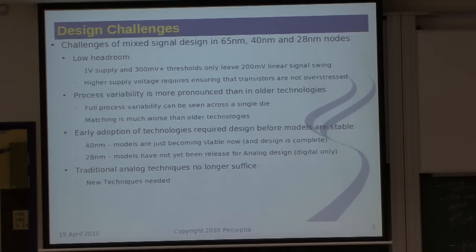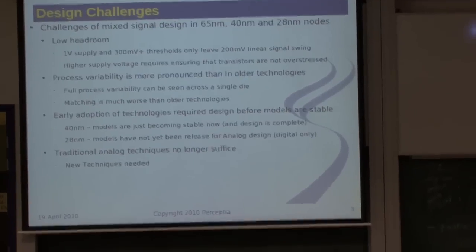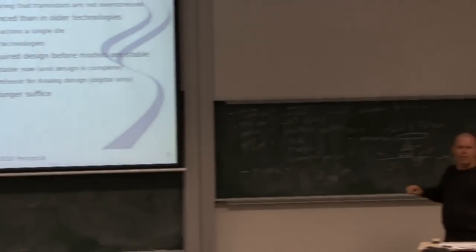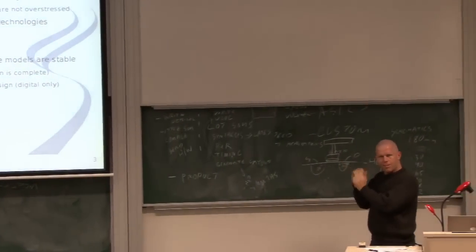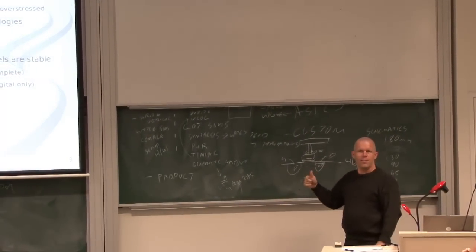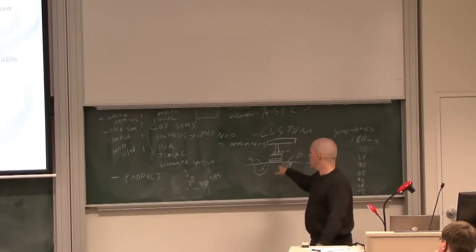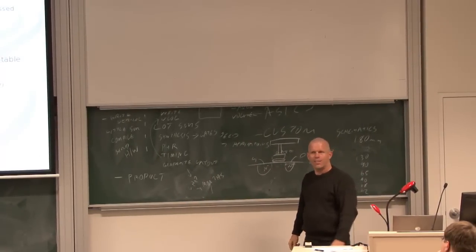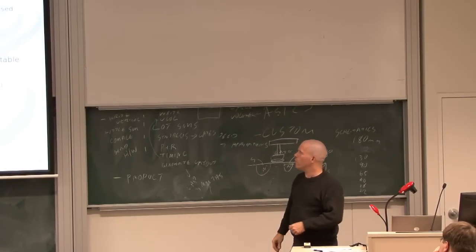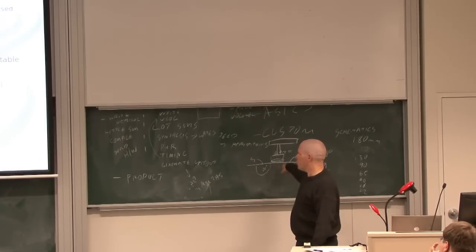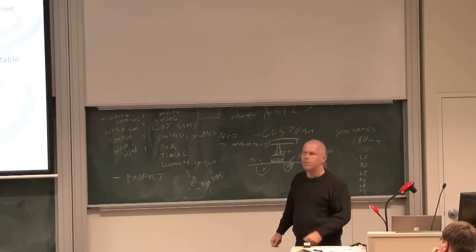If you put 3 volts across a FET, you create an electric field, and the closer you bring them together, the higher the electric field gets, until the point where you simply can't turn it off. The electrons drive through. So as we get smaller, we've got to stay within physical limits.